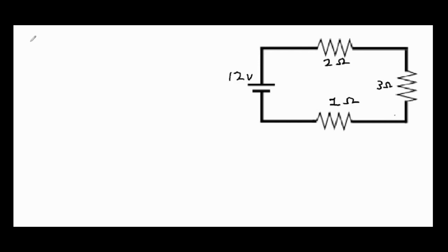So first of all, we have three main components. We have voltage, I for current, and R for resistance. So making sure you understand each one of those is going to be a key component. Voltage is the potential energy per charge. The current is the rate of flow of those charges, and the resistance is basically anything that is opposing that flow.